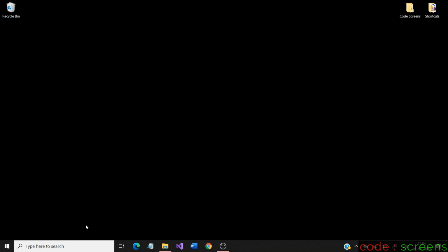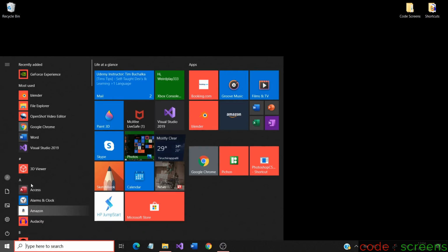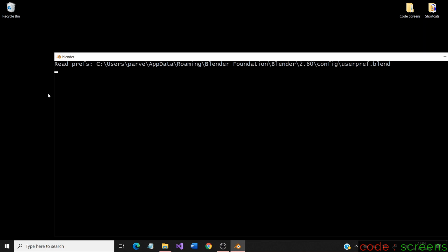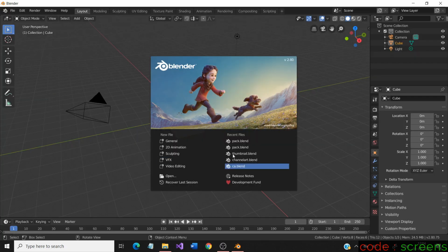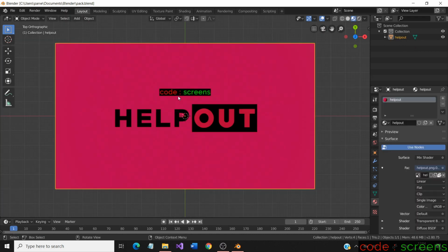Now the image is not available in the system as an external file. But inside the Blender file the image would be present due to the pack option. This can also be used when the file is in its native system but the image used is deleted. But use the pack option before you delete the external file.